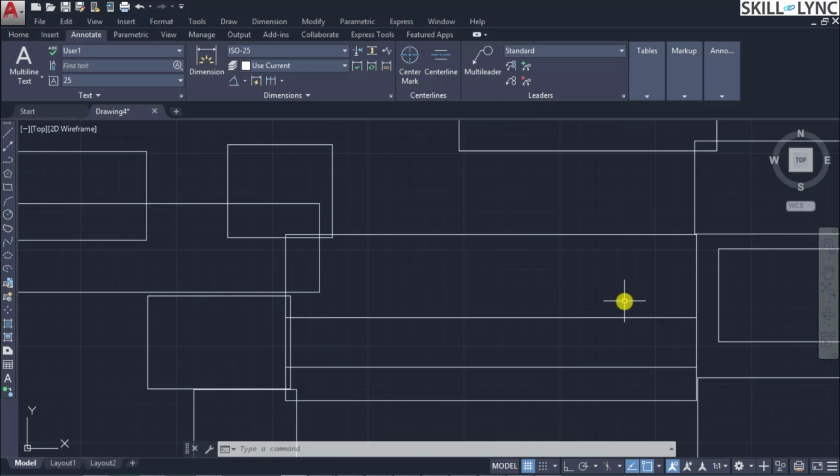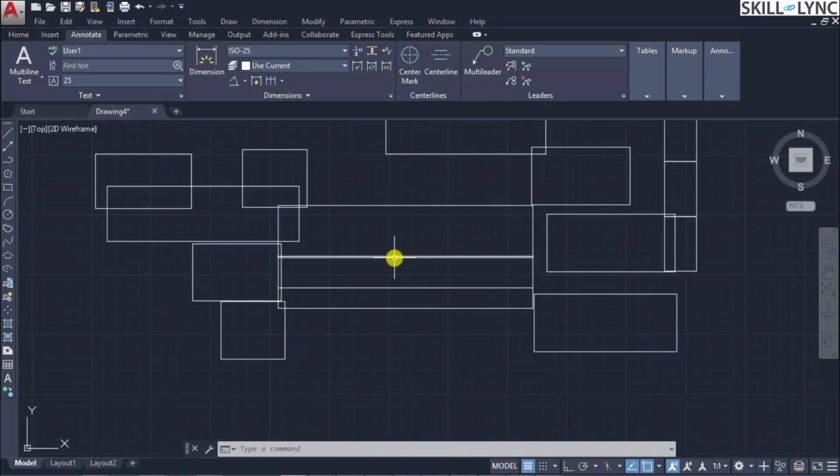So now you can still focus on your work area. Why this is useful is because you can differentiate what your text objects are and you can selectively mask them to improve your performance. But if you still want to hide all those things that are available here, then you can do that using the layers command that we'll see in the subsequent week.